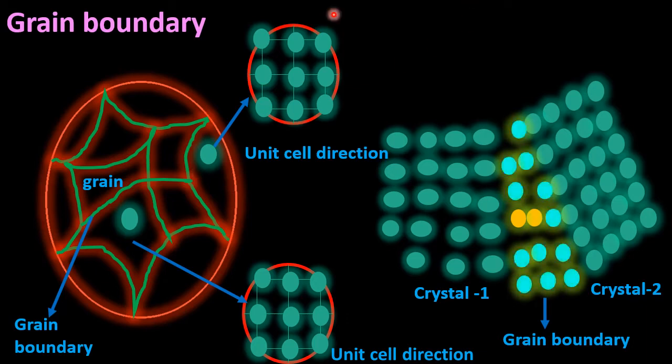So these properties, like bulk modulus and electrical conductivities, will be different in different directions, but as a whole specimen, which is composed of a grain aggregate, it will behave isotropically. Although the individual grains behave anisotropically, the material as a whole specimen, which is the aggregate of all grains, will behave isotropically.